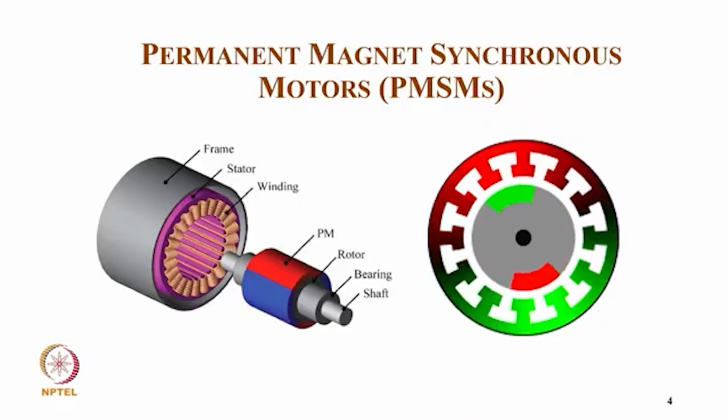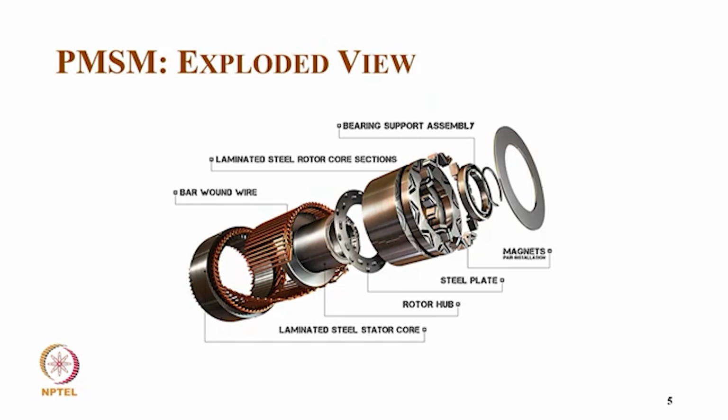This is the basic idea, and you can have a more detailed configuration here, of how on the rotor we have sometimes an LNC also. This is a new concept with the flux barrier, where we put rare earth magnets, and the barrier will also work like air. So we have a good torque, especially for the electric vehicle industry, a very good torque due to saliency as well as due to the permanent magnet.